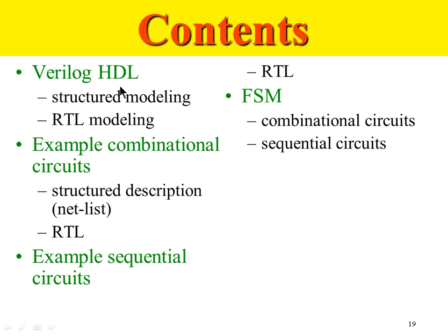Earlier there were a lot of languages. Later on, it got standardized to two languages, Verilog and VHDL. Both of them are called HDLs, Hardware Description Languages. So sometimes you will see HDL or sometimes you will see the RTL terminology used. It's the same thing. So a digital design can be developed using Verilog with the structural modeling concept or the RTL modeling concept. RTL modeling is also called behavioral modeling. We'll see what all this means in the next few slides and classes.